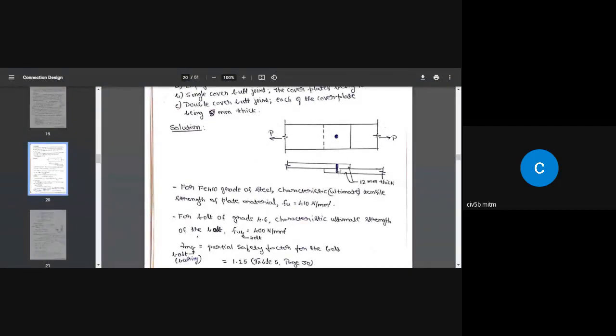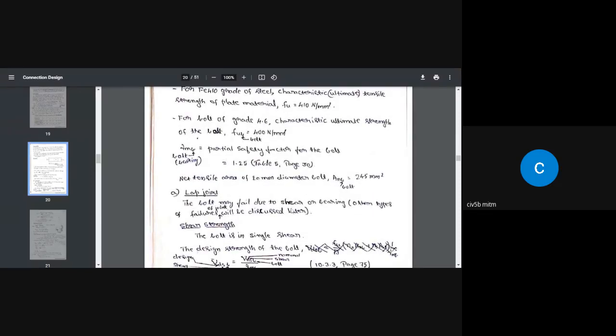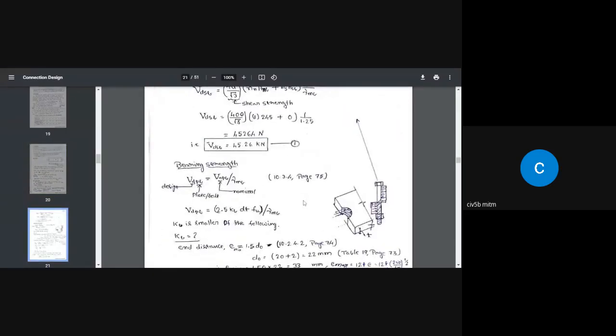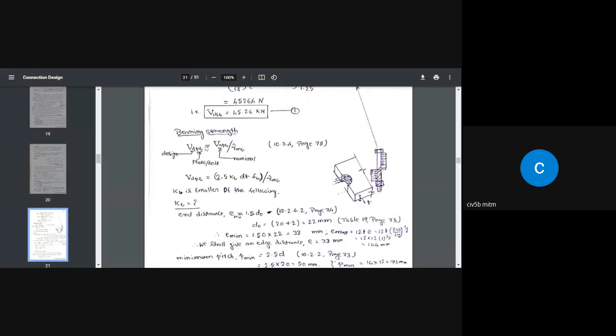That is through bearing, because when you pull this, the area of contact gets, due to the contact, the material fails or yields. Similarly on this side. So we need to find out what the bearing strength is.